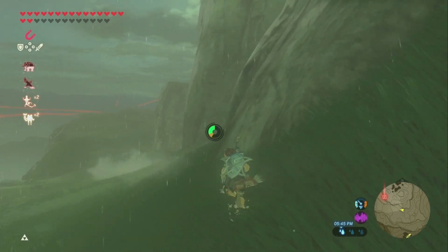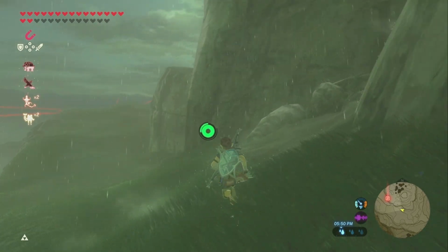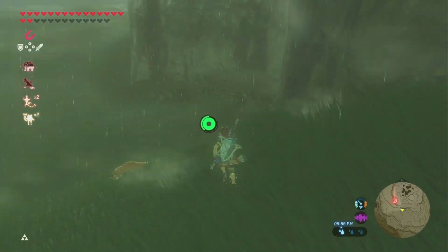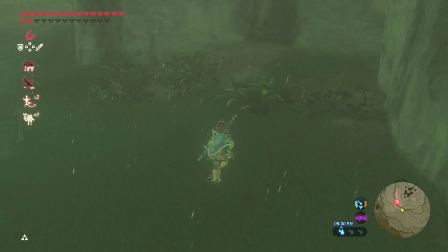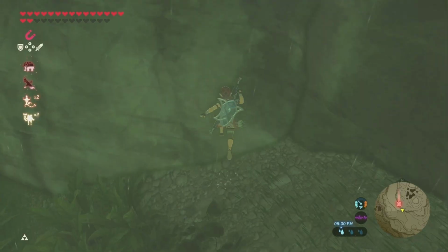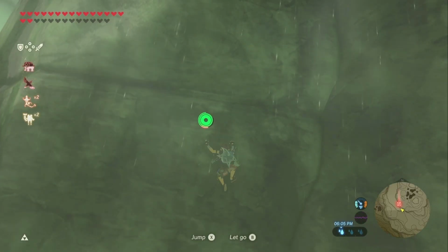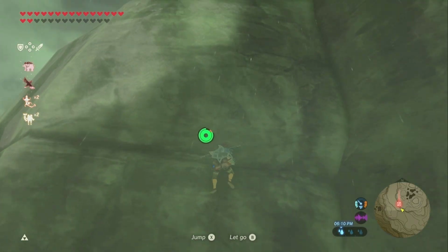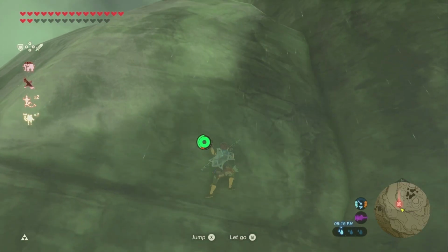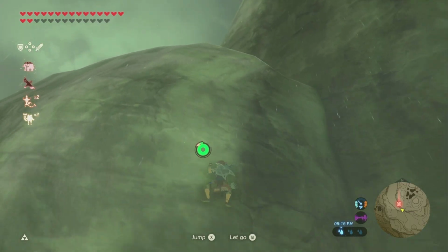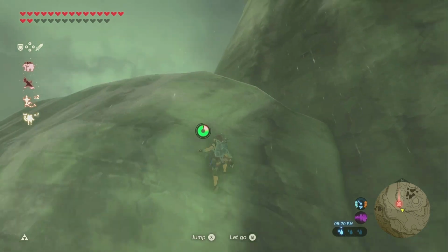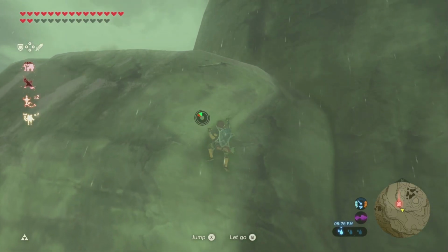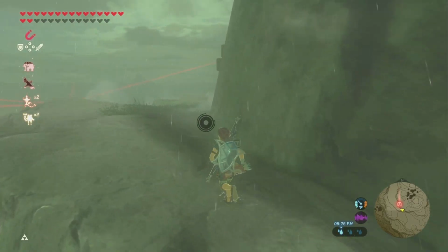Okay, and now it says number 2, drain valve problems. Water heaters should have a drain valve at the bottom. The valve may be missing, damaged, or leaking. Causes: you already know. This can be an installation issue, mechanical damage issue, or lack of maintenance issue. Implications: if there is no drain valve, it will be difficult to get the sediment out of the bottom of the tank. This affects the efficiency and amount of hot water available. It can also result in noisy tanks. If the valve is damaged, it may not be operable. If the valve is leaking, obviously water damage is a possibility.